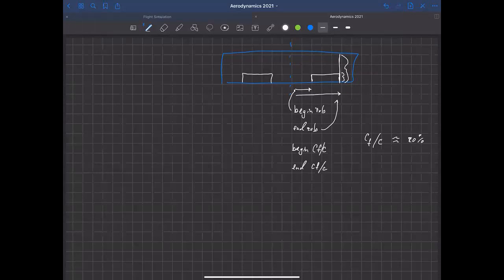So, we've set up our wings. We're using lifting line theory, and we have these places here that are cosine clustered spanwise locations. These are the nodes along the wing. And so the user put in this definition for the flap geometry, but it's actually only going to influence our solution for anything that lies along one of these node locations that we're looking at along the wing. That's the same with the geometry as well.